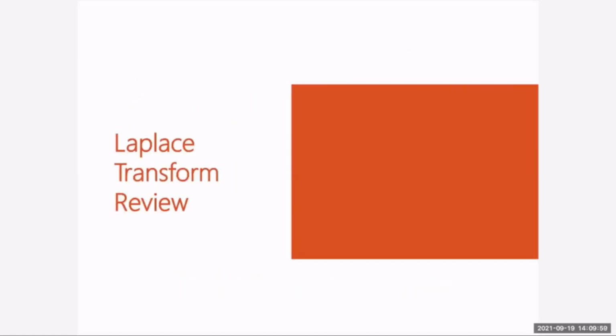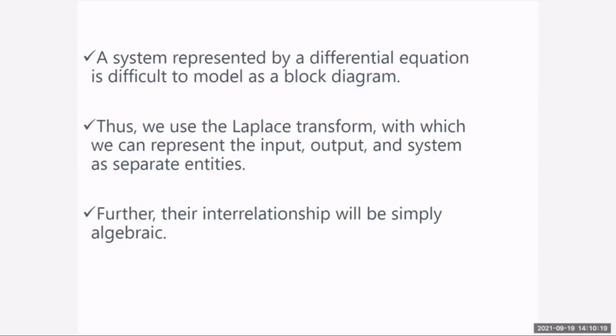We have here the Laplace transform review. It would be just a review for you because this had been a topic in advanced engineering mathematics and differential equations, wherein Laplace transform had been introduced. A system represented by a differential equation is difficult to model as a block diagram. Thus, we use Laplace transform, in which we can represent input, output, and system as separate entities. Further, their interrelationship can be simply algebraic.